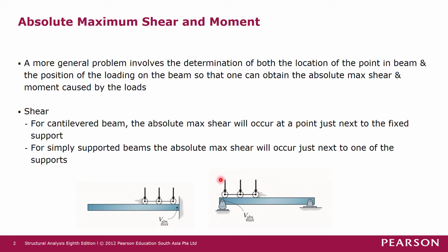So move all these three forces with this force very near to this support to get the maximum shear force at this support. For this type of beam, for shear, we can get the values by just visual inspection on how we arrange the loads.